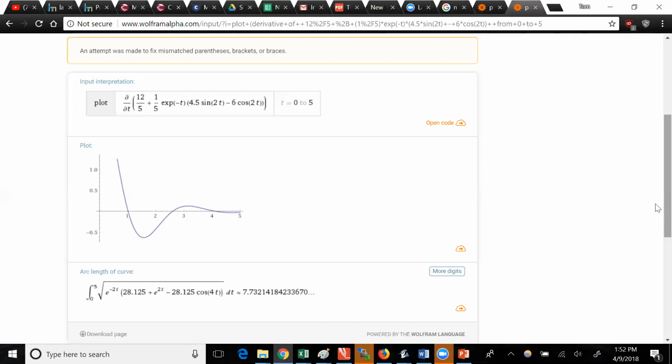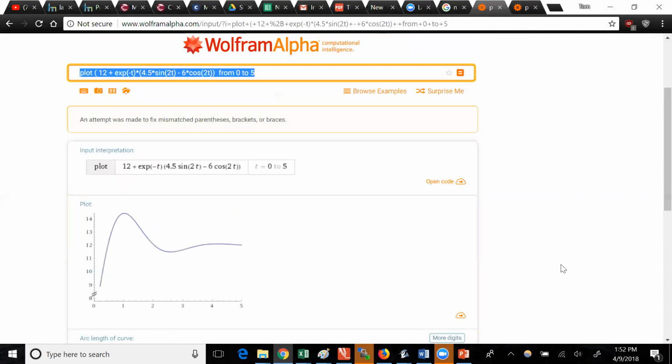And what's happening again is the energy is shifting. Initially the energy is distributed between both the inductor current and the capacitor voltage. There's some in both, and after the switch throws, they're circulating the energy back and forth until finally the capacitor ends up with all the energy. The inductor has dumped all its energy because there's no current flowing, but the capacitor has charged up and is storing all the energy at the end. I think of it a lot of different ways, like a slinky, where stuff is moving back and forth for a while until it freezes.